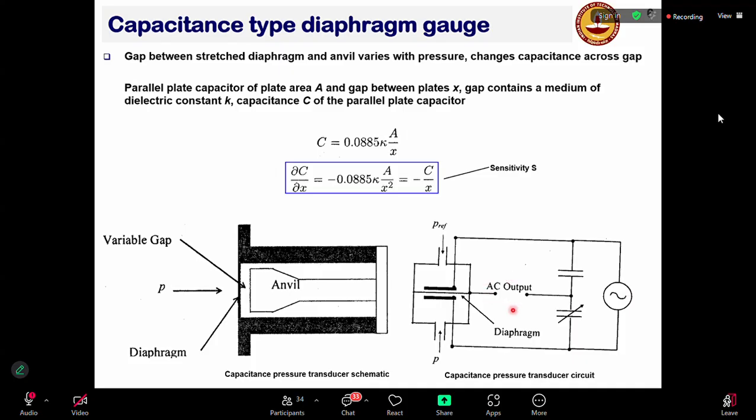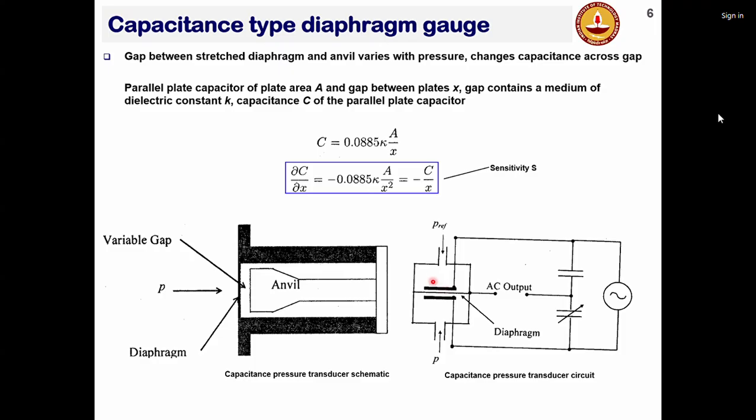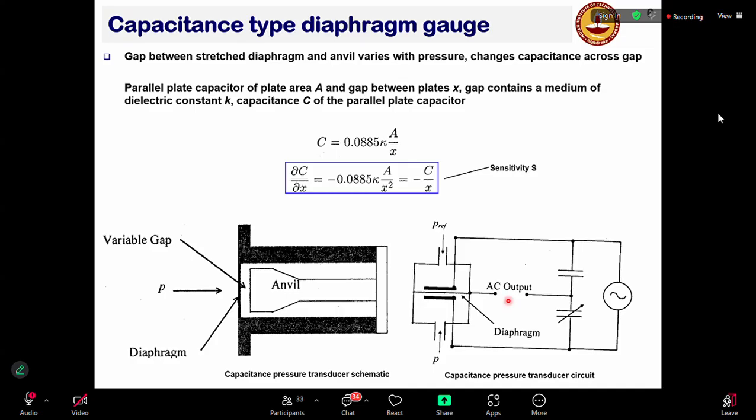Yeah, there will be no current, but there will be a non-zero output here. Oh, why, sir? I could not gather it. See, the mechanism behind that is, when this deforms, the amount of charge that will be stored here and here will be different. Okay. So now by varying the capacitor, you are basically equalizing the current. But since the capacitance now is different on these two circuits, if you do a circuit analysis, you will see that it will result in a non-zero output. Oh, yeah. Basically Q1 upon C minus Q2 upon C, right? Yes. Okay. Fine.